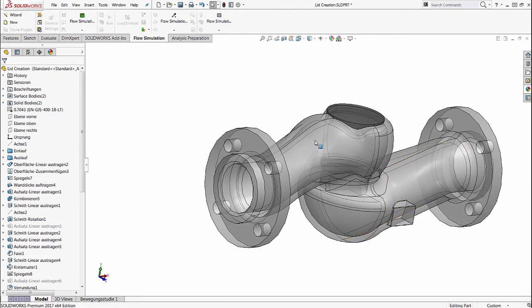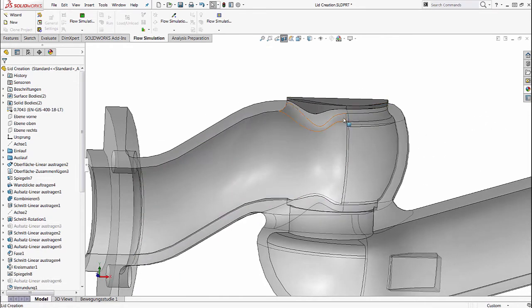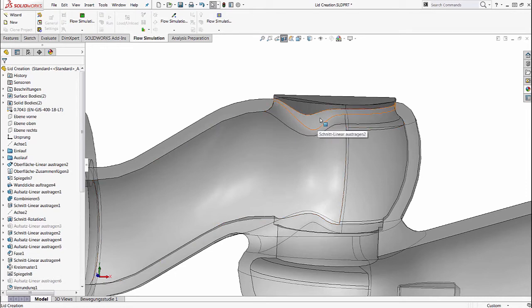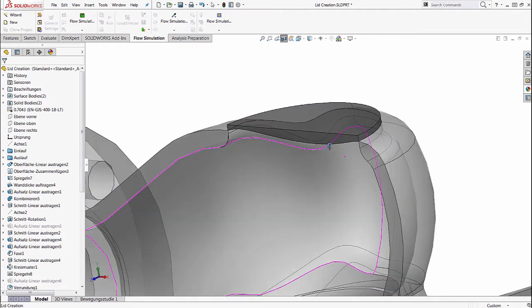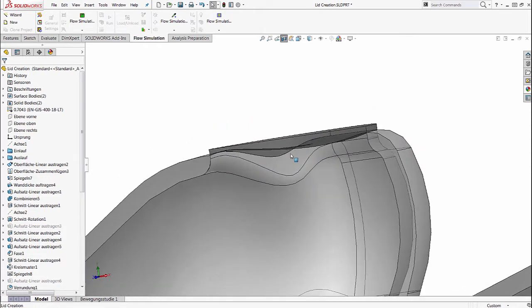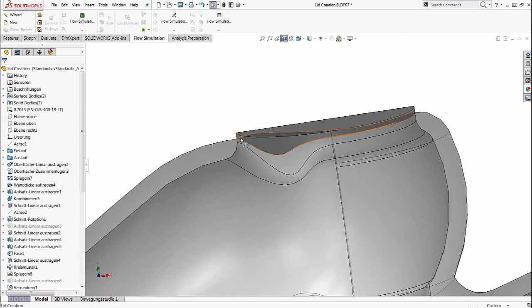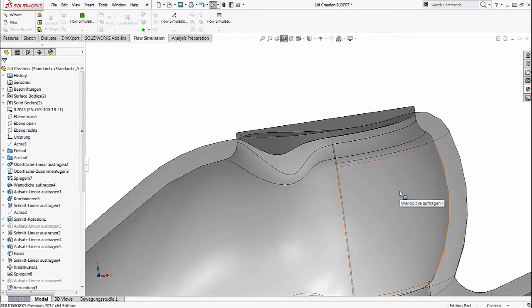The second thing I want to talk about with lids, let's go ahead and just look at a cut plot, a section view. And I want to talk about this opening on the very top. If you intend to use this opening to define a boundary condition for your internal analysis, a small amount of post-processing is needed because without the lid that's been created here, there is a curved opening and all boundary conditions must be applied on a planar face. So in this case, because this face was curved on the very top, a lid was created manually where you can go in, apply or define some geometry to make sure that that's closed. Typically, it's recommended to have a very small extrusion on the very top so that the actual dynamics of your flow is not much different as compared to the initial shape that's been defined.